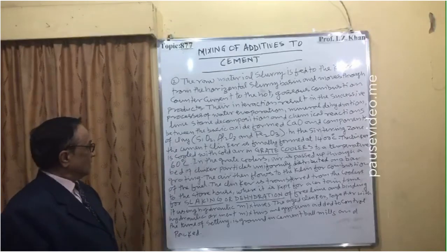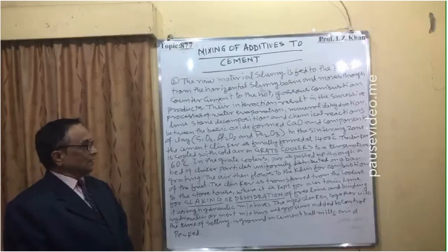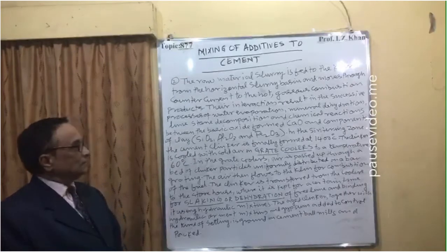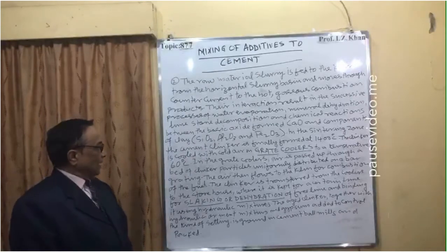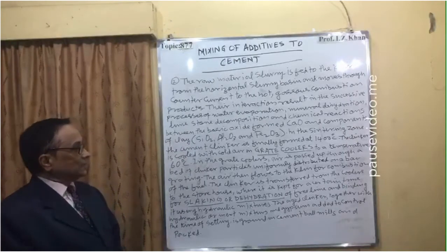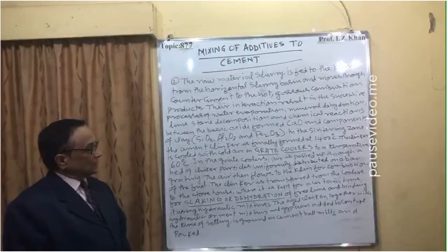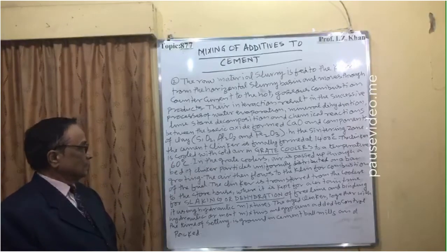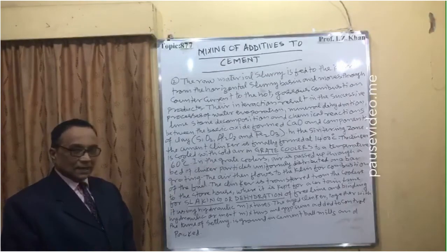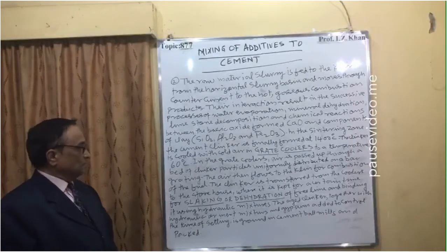The clinker is cooled with cold air in the grate cooler to a temperature of 60 degrees centigrade. In the grate coolers, air is passed up through a bed of clinker particles uniformly distributed on a bar grating. The air then flows to the kiln for combustion of the fuel.